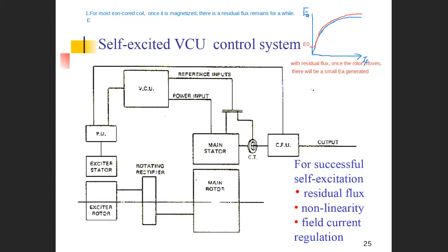So the field current is the field voltage over the field resistance. Because of the self-excitation, for your easy understanding, we write down here that the field voltage is the terminal voltage, with the field resistance, which furthermore is the internal generated voltage minus the armature current times the armature synchronous impedance, over the field resistance.